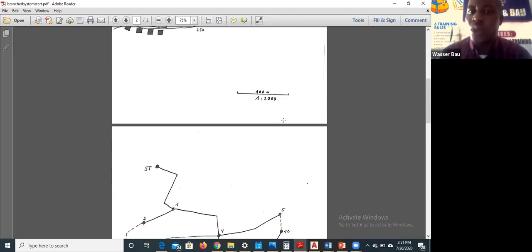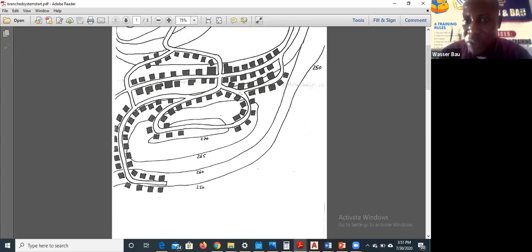So let's go back to the drawing and see. If you look, node 9 is here. Based on this 10 that I put here, there is no house on node 9. Why? Because this 5 and this 5, I've included for node 10. Then this 5 here and this 5 here, I've included for node 12. So I can correctly tell you that the base demand for node 9 is 0.